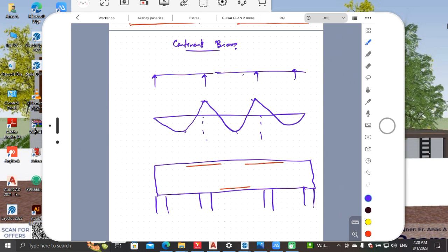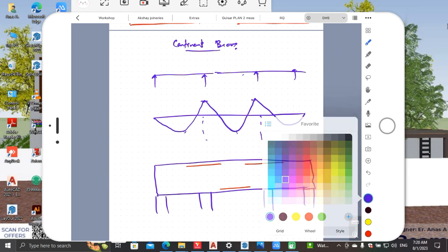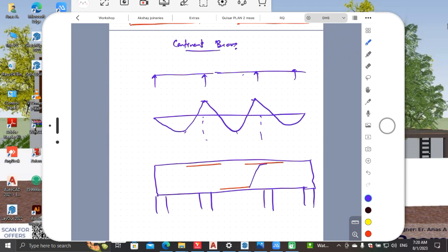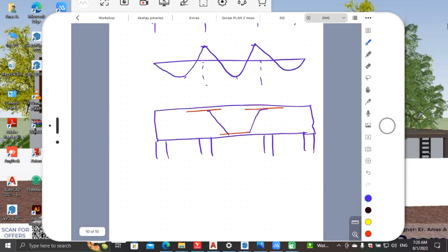And here we have the tension reinforcement. This is a type of curtailment, and you can also keep the curtailment like this also. So, in order to keep the cage structure, we will be extending this thing like this. We might be needing this reinforcement only at this portion, but to give that cage-like structure, you will be extending this at the middle also. That is use of additional reinforcement. In bottom also, we will be extending it to that part.